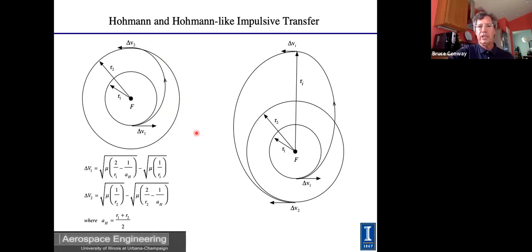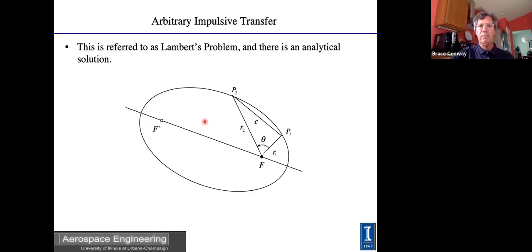And so if you look at the history of Mars missions, you'll see that they take advantage of the Hohmann transfer and launch about every 26 months. And a back of the envelope kind of calculation of the delta V required will probably get you within a couple of percent of the actual delta V. Of course, it's ignoring things like the gravity of other planets, solar radiation pressure, and so on. But those are relatively small, and it's reasonable to assume that the spacecraft is moving on a Keplerian ellipse. So you can do a very good back of the envelope calculation of the velocity change required.